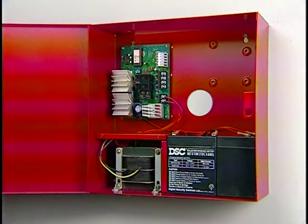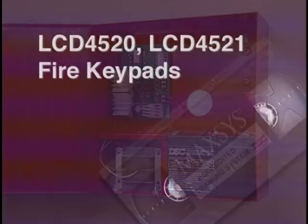The module comes in a PC4052CR red cabinet with a hardwired 28-volt 175 VA transformer. Because this module provides 24 volts, there is room in the cabinet to house and connect 2 12-volt 4 amp-hour batteries. The battery jumper cable provided allows you to easily connect the batteries in series.